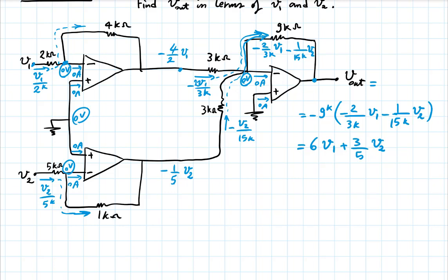The purpose was to not directly connect two nodes on which different voltages have been imposed, right? So I wanted a resistor between those two nodes, so as to avoid that previous contradiction on the circuit, or conflict. I chose the value 3K, you might say arbitrarily, or you might say because I wanted it to be something that 9 can be divided by, or maybe it appeals to one symmetry. This is just an example.